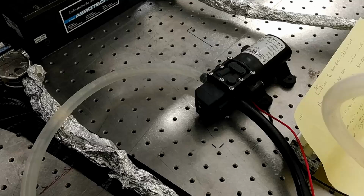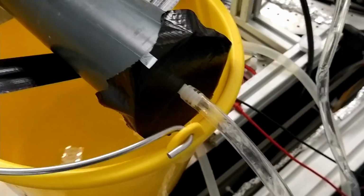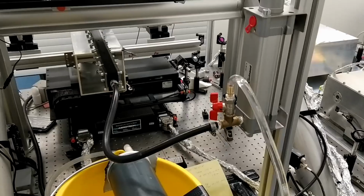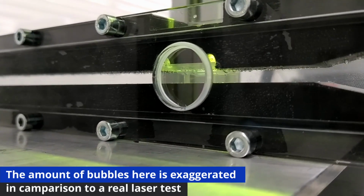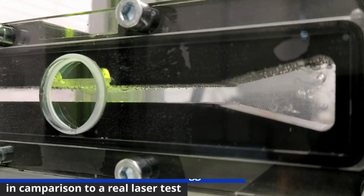The second issue was that there still seemed to be some PIV particles in the fluid. To get rid of these particles I used a filtration system that pumped the water through a micron filter. However, this did not seem to solve the problem. It seemed that the particles are bubbles instead, which are probably introduced by a badly vented pneumatic cylinder. As I was running out of time for my thesis, I proceeded with the laser test anyway to make sure the test system works. Here are the test results of the laser test.